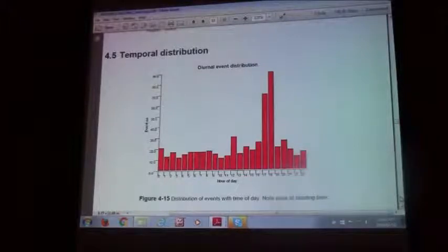And you certainly can. The question is, would it change your seismicity? The research that we've done has said no: the amount of seismic energy that gets released is proportional to the amount of mining you do. It's to the volume of rock you extract, to the change in energy balance that you do. So whether you mine by blasting or by cutting the rock, non-explosively, you're likely to get very much the same amount of seismic energy.